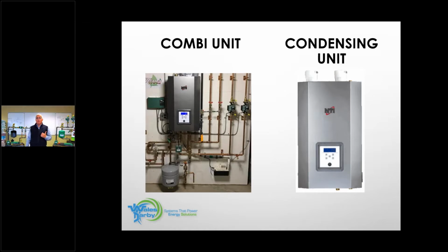So we want these boilers to condense. And the other difference is the venting and the piping. The venting is going to be different. These are 2-pipe boilers. I got to bring in outdoor air. We don't want to use room combustion air. We would need a lot of room area, and you probably have a lot of clutter down there. You probably have your laundry down there. I don't want to bring contaminants into that boiler. And I want to make sure it's going to condense.